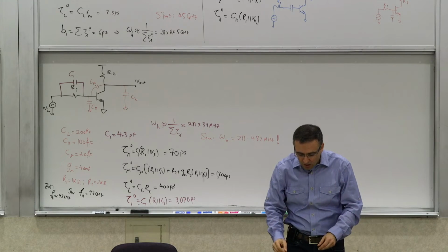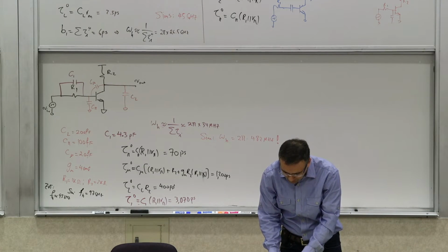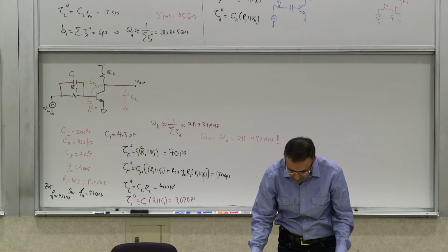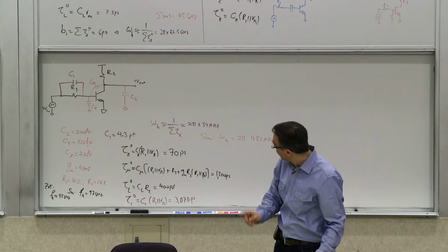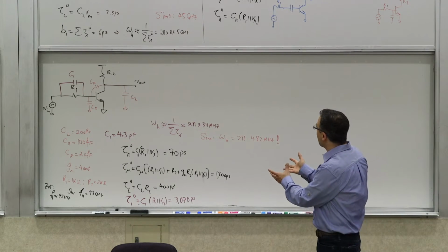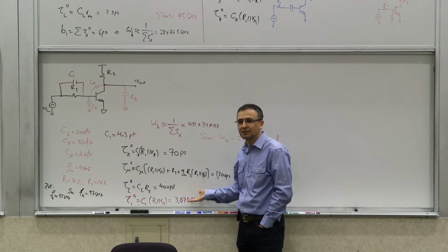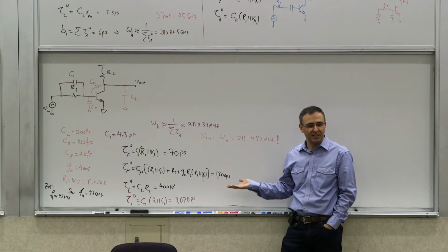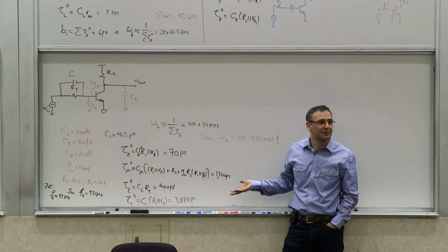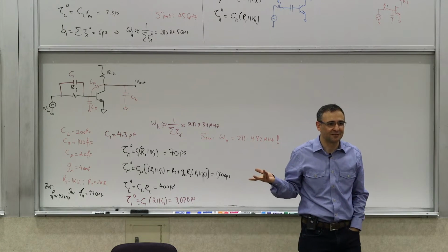What's happening there? Okay, so how do we choose that? How do we pick that value? We'll see in a second. But let me do another example, and then that will lead us to the modification needed. So you can see that as a bandwidth estimation, we have failed. ZVT has failed here, really. I would consider this a failure, right? If you're more than an order of magnitude off, you failed.